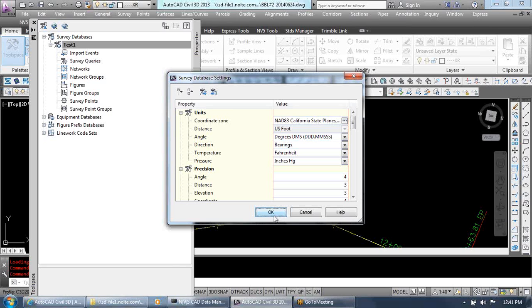I would say leave it in the file, make like an existing point file, that's where we load all our points and keep it in there. But then we start talking about databases, and it's like, well, no, we don't set it up, we don't get all the points for this field office. We just get a CSV and we bring it into our drawing. Yeah. But that's what you guys should be doing then, setting up your databases for everybody? Well, no, because they don't work the same as they used to on desktop. Like, you can't link them to multiple drawings. You have to export your database and import it into the drawing. So you still have to do the same thing. It's just not so survey friendly.